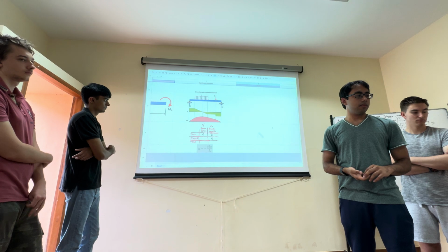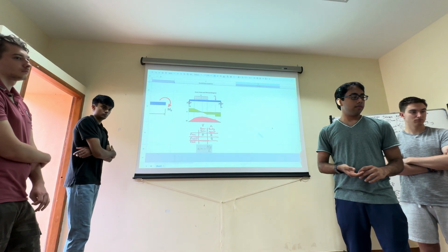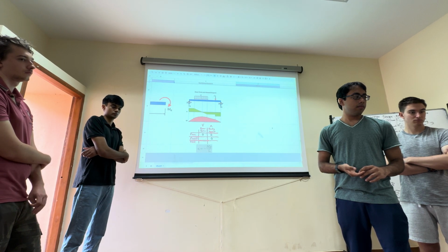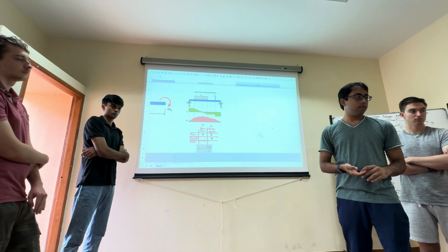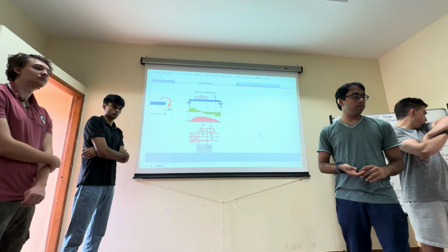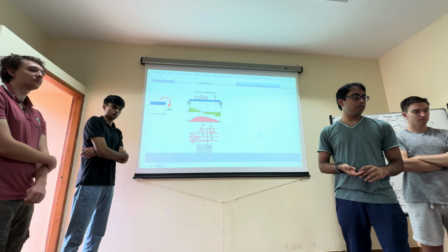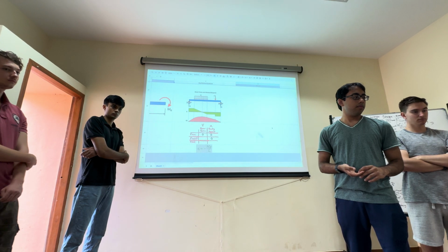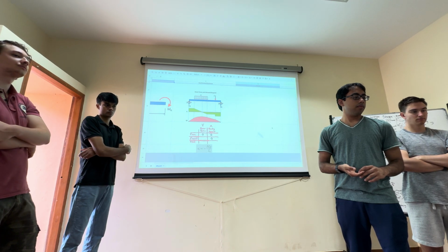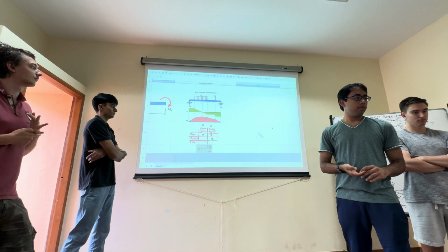Yeah. So for example, I can take a free beam like this. So I can apply forces like this. So it's not actually supported by anything, but it will still have stresses. Yeah. Okay. So on the other hand, I could replace these two points where I'm applying the load with actually supports. So when I have supports like this, you could probably think of it like if it's hinged, a simply supported kind of beam structure. So yeah, those are three different kinds of typical idealized boundary conditions.